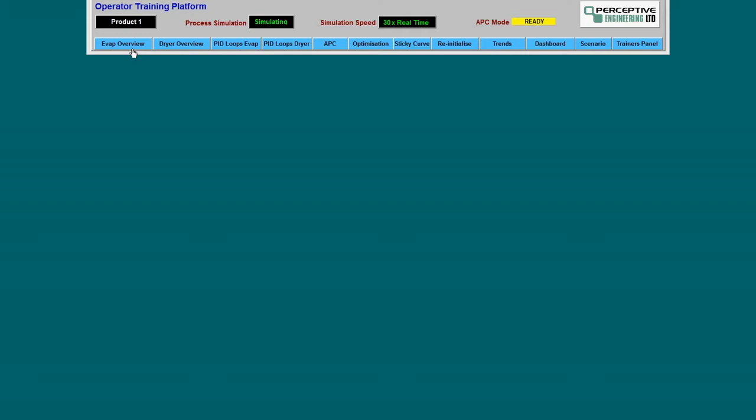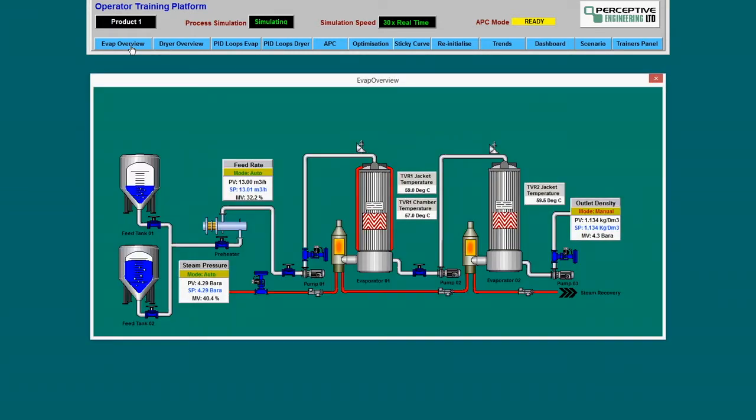Alternatively, the operator can monitor a real plant scenario, take action as required, and compare the performance to what actually happened. OTP models are simply used to generate process responses and represent all the input-output relationships that have been modeled on the process plant in question. PID loops are also simulated so the behavior of the PID loops can be monitored. Operator actions can be made during the simulation to move the process to new operating states, such as those with higher throughputs or lower solids, for example.